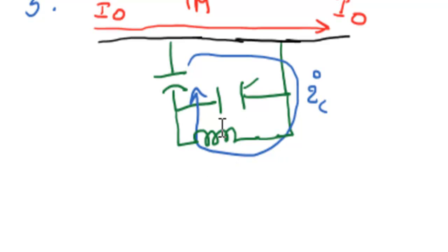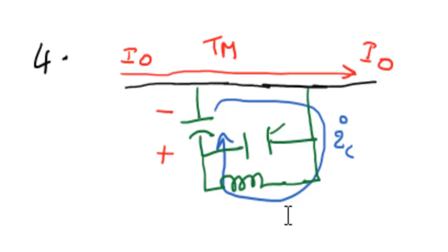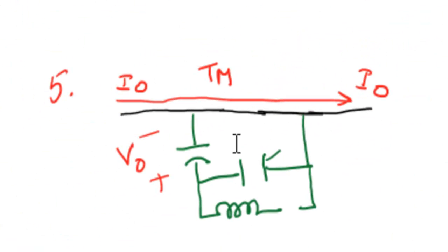Once the current reaches the maximum value and the voltage across the capacitor becomes zero, the energy available with the inductor starts transferring back to the capacitor. In this case you can see that voltage starts building up across the capacitor, but in the reverse direction, because the current is flowing through the capacitor like this. Earlier it was discharging, acting as a voltage source. Now it is charging, so it acts as a simple load. So the capacitor voltage will be building in this way. After another pi by 2 radians, the energy available with the inductor is completely transferred to the capacitor. That means the voltage across the capacitor becomes maximum, and the current flowing through the inductor will be minimum, nothing but 0. So this is the situation.